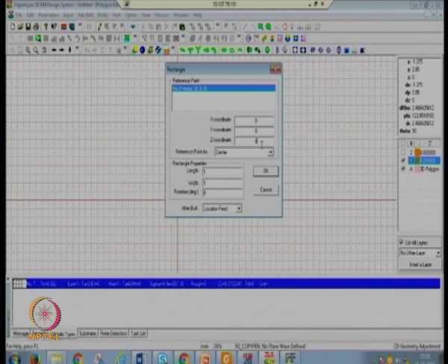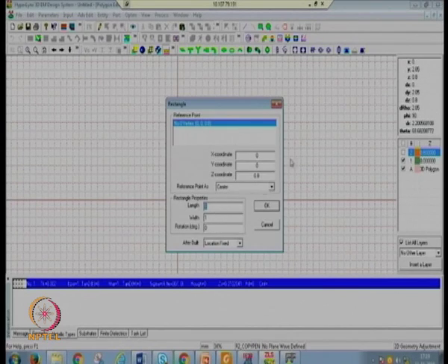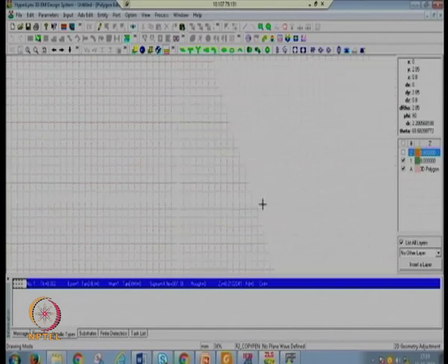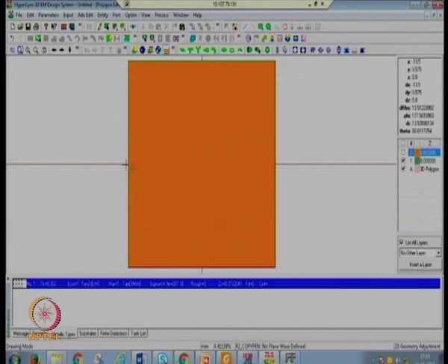So the z coordinate should be 0.8, but by default the layer selected was z equals to 0. So let us select first this coordinate. Now you design. Now you can see here z coordinate is 0.8. So it will depend which layer you select, accordingly z coordinate will be shown here. So the length should be 16.74 and the width should be 16.74 to design a square MSA. Now just click on all, you can see the geometry. This is my square polygon.